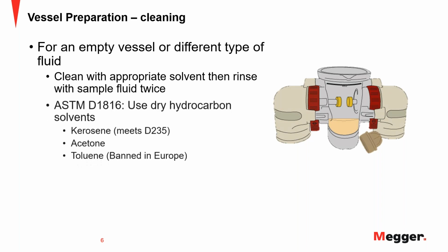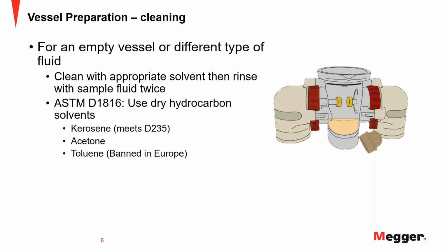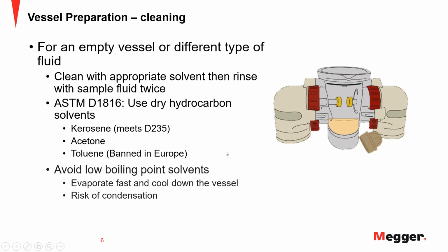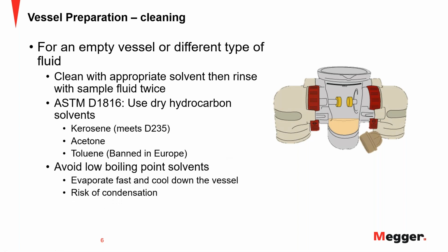ASTM recommends the use of dry hydrocarbon solvents, and some of these could be kerosene. This meets ASTM D235. You can use acetone or toluene, however, not in Europe. The main thing here is to avoid any low boiling point solvents, because they evaporate quickly, and that has a cooling effect on the components that the solvent is in contact with.